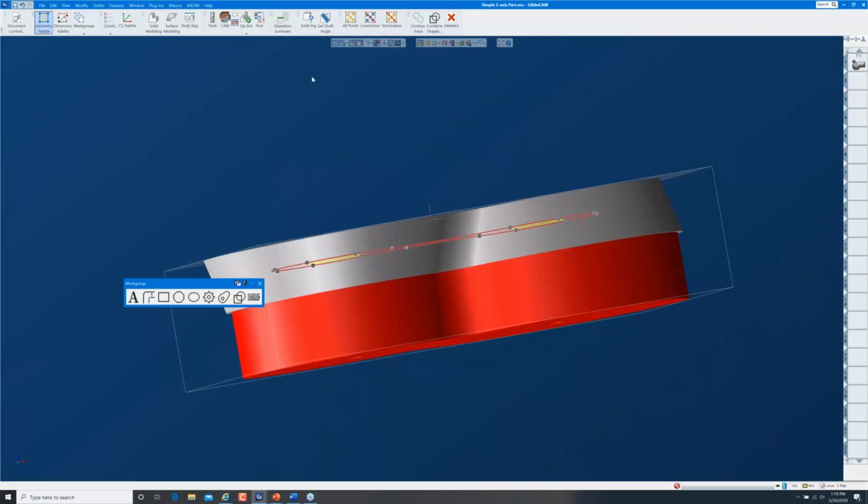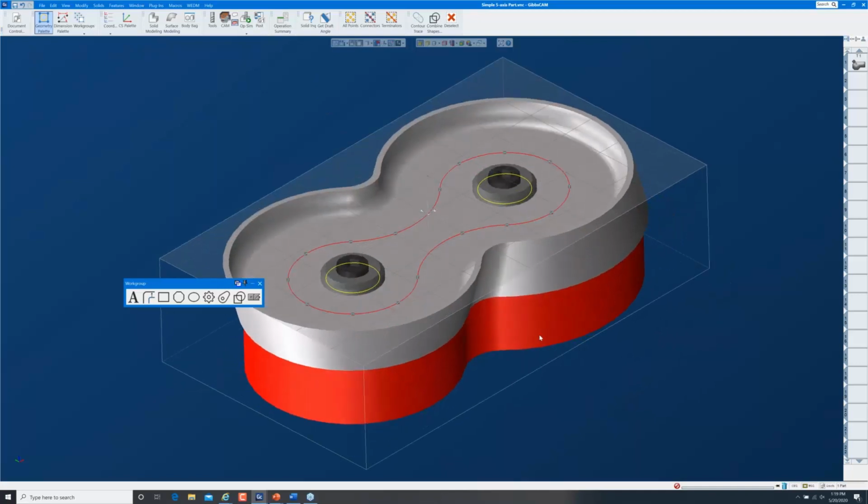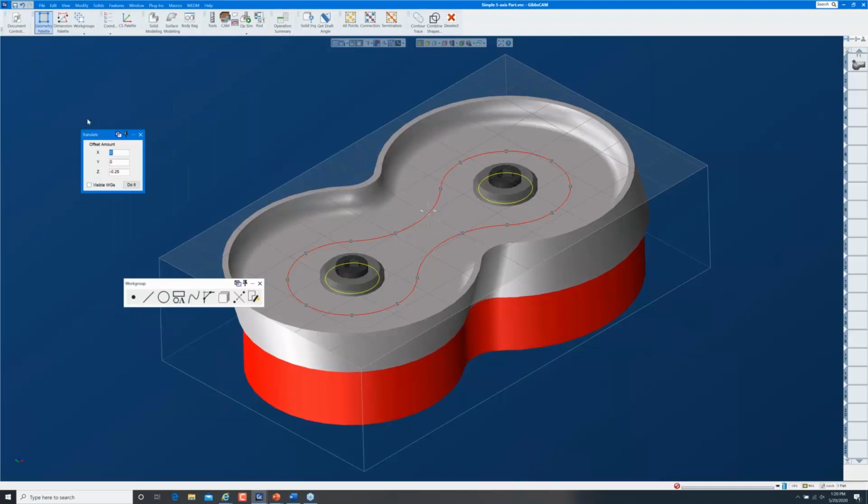However, with it being down on the floor of this pocket, it really doesn't do me any good, because if I project the center line of my tool through this, I'm still gouging, so I need to modify this somewhat. So I'm going to translate this up, and I'm going to go, say, a 1/2 inch a couple of times, and maybe one more time. So that's 1.5 inches above the floor of that pocket.